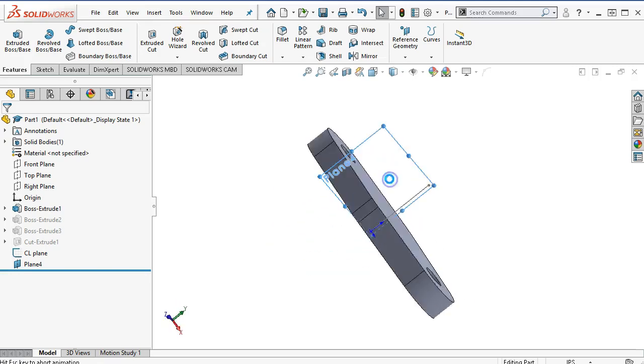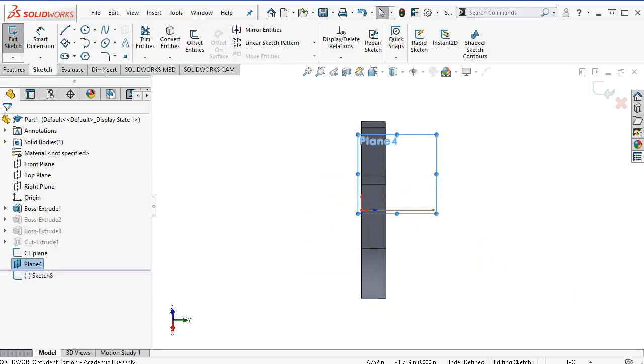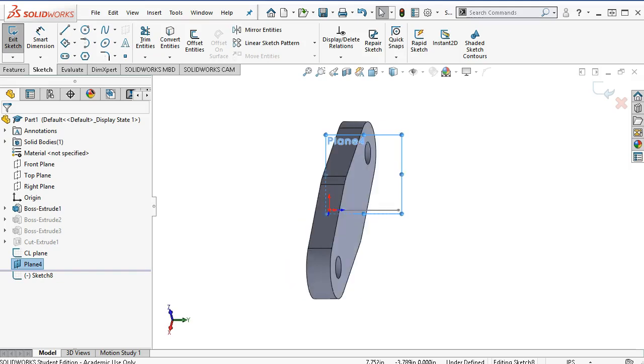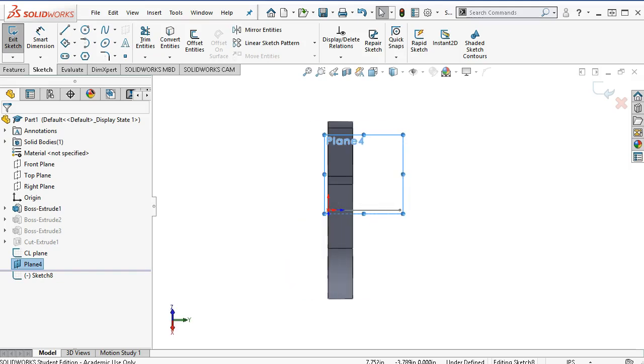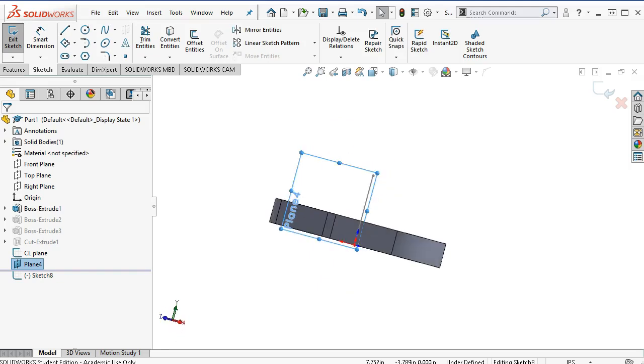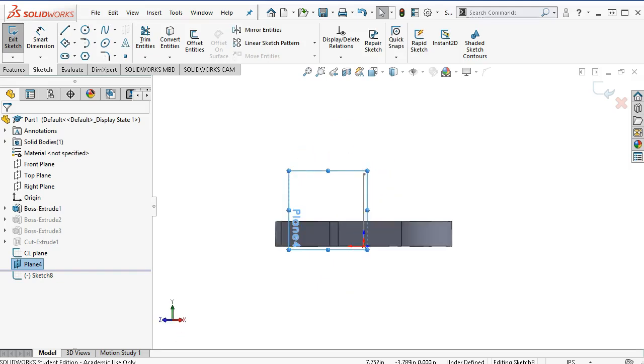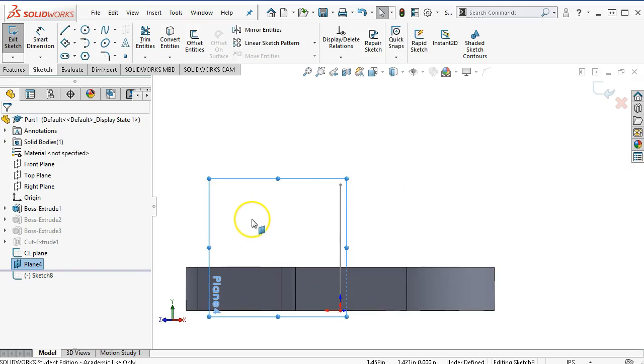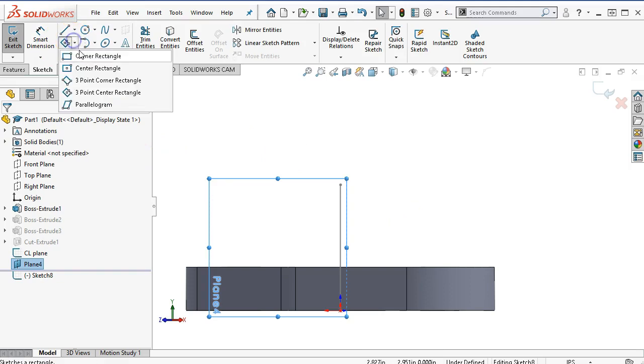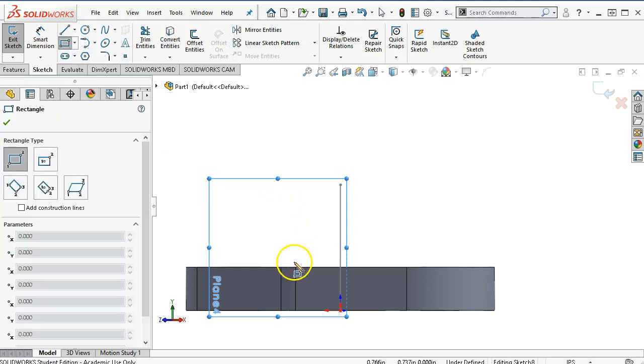All right, so opening up a sketch on plane 4. Well, it did the rotation, so I was looking for the rotation. Alt and the arrow keys on the keyboard will rotate me back into position. So in this sketch, when we're applying the relations, we just have to be aware our vertical is left to right and our horizontal is top to bottom, which is kind of weird, but will work.